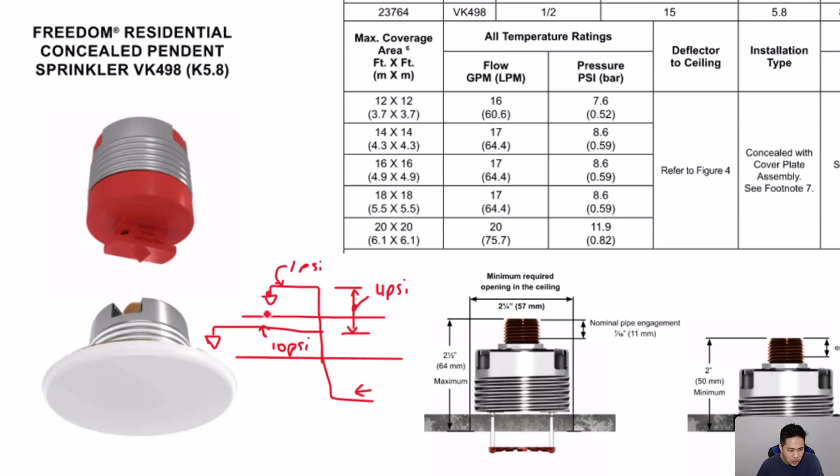And this is the sprinkler head, and this is a sprinkler head on a lower floor. This height elevation, let's say you lose 4 psi, that goes basically from this point here to this point, and then you have 1 psi of friction loss in the piping. So the total loss from this point here to the sprinkler is going to be 4 plus 1 psi, so you have a 5 psi loss.